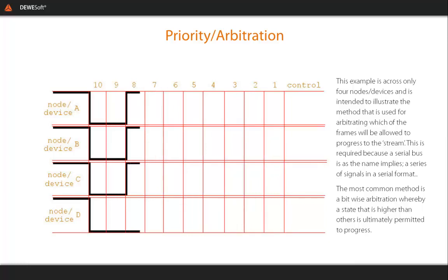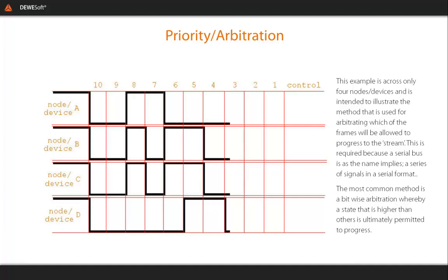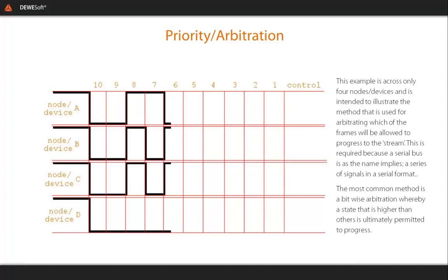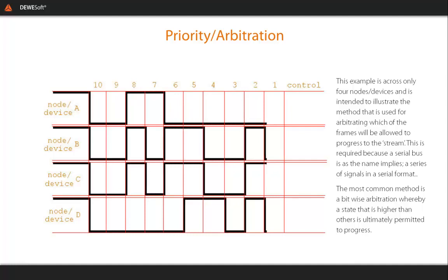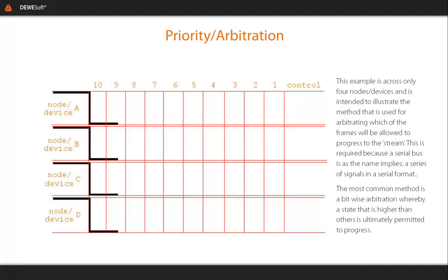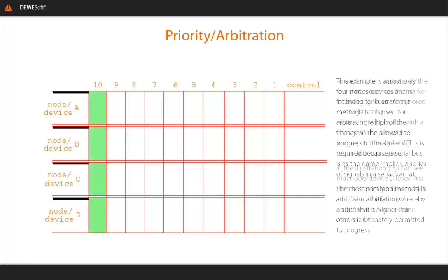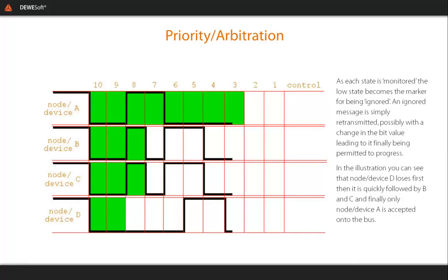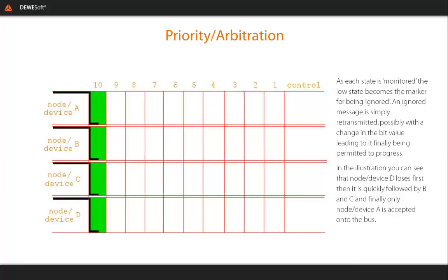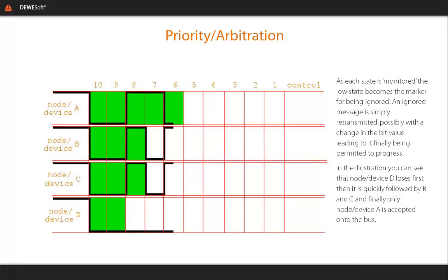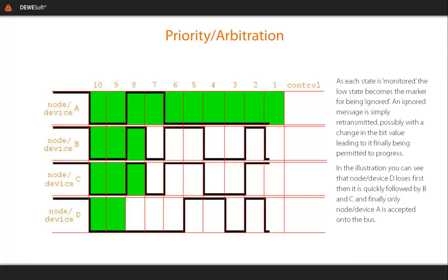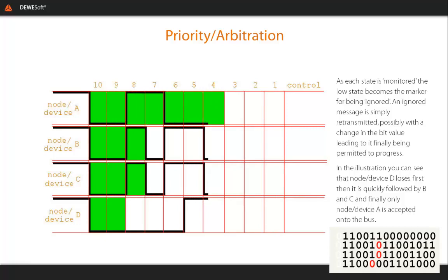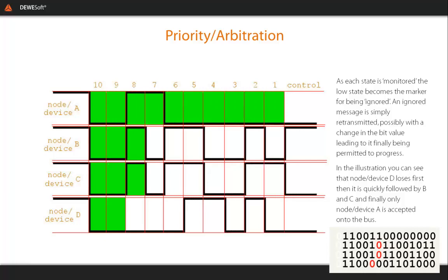This is achieved using prioritization and arbitration. Now, note that FlexRay has no arbitration as it's time driven. In this example, we see 4 competing sets of information trying to get heard, and only one can be. Now, in this you can see that one message is effectively one arbitration. It ultimately will make it through to the rest of the network, including you if you're attached. However, at this point, it is worth getting familiar with binary, as it demonstrates much clearer the mechanism that allowed the message to get through.